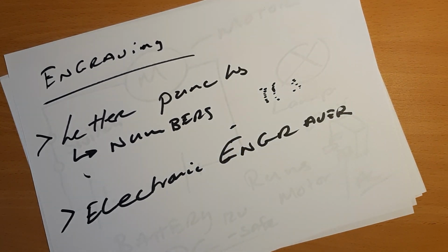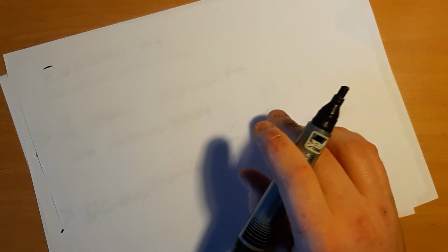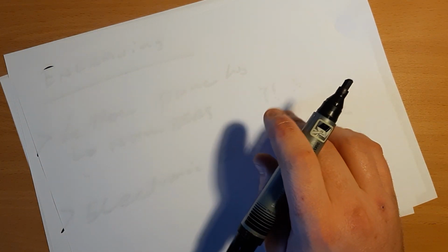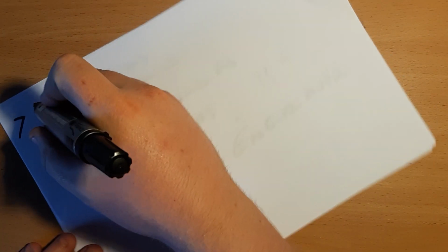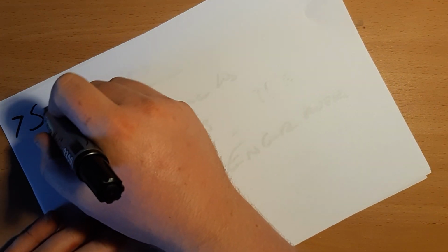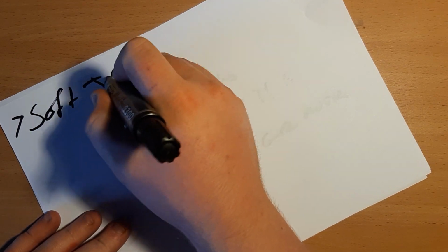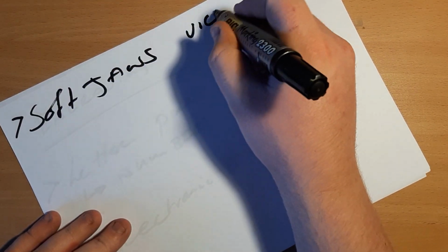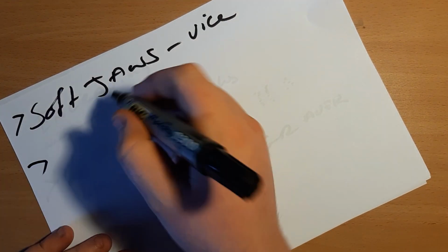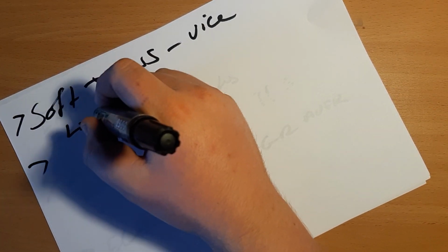And briefly describe how you would achieve a high quality finish on the assembled model. So again, I was talking about how when it comes to assembly, all marks, first of all, you need to start thinking of how you would make sure that it doesn't happen in the first place. So you need to be doing the simple things right, like the likes of soft jaws in the vise. That'll prevent dents on the piece.